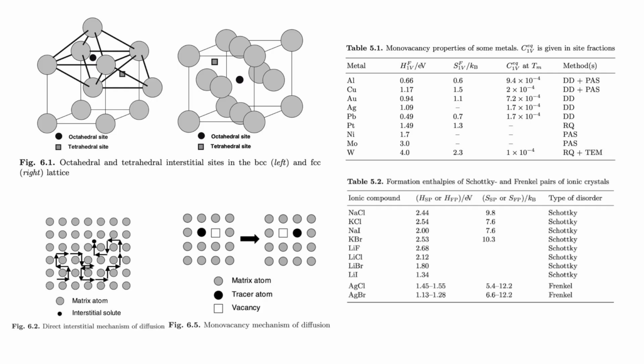So specifically, we use the carbon diffusion in iron as an example to look at this interstitial diffusion mechanism. For the vacancy diffusion mechanism, it's actually pretty straightforward. There's a vacant site that is just going to jump, and the jump distance generally is shorter compared with an interstitial jump, as you can imagine. From one interstitial to another interstitial, sometimes it's longer.